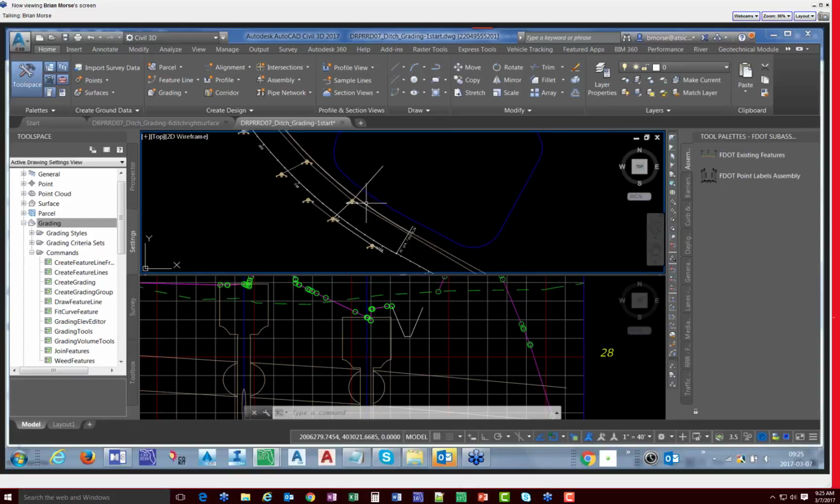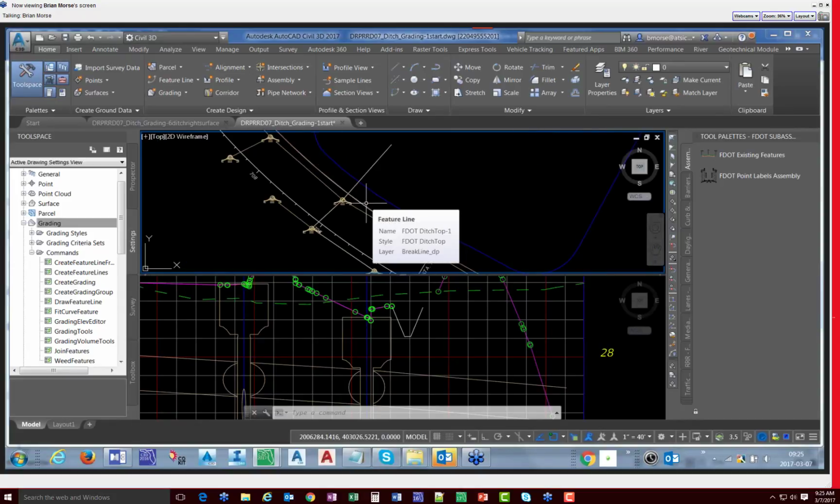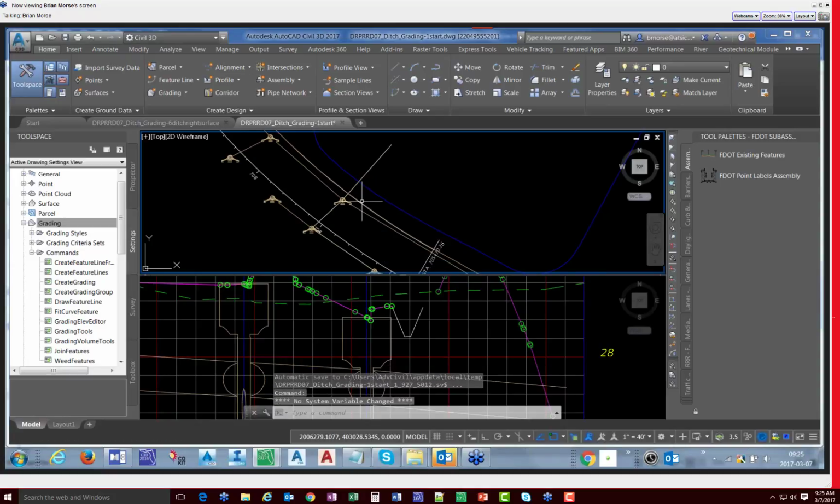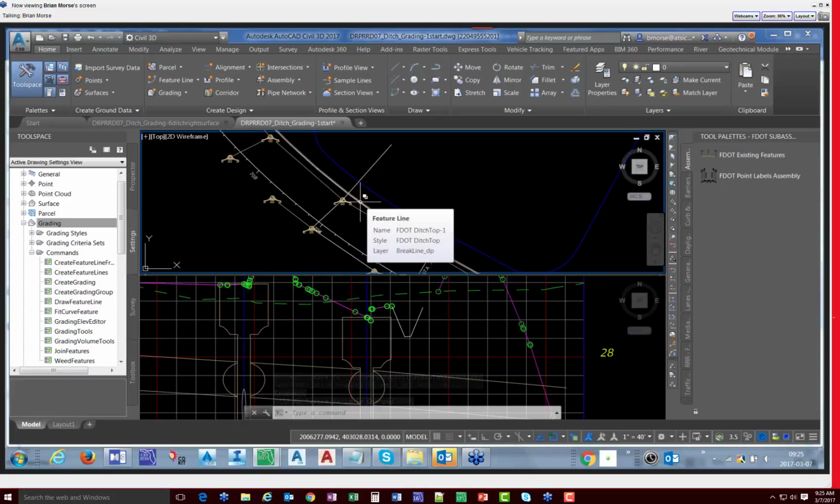So we're going to confirm this. If we go 49 feet plus, let's say we wanted to go 6 feet out, because that's going to be at a 4-to-1 slope, it'll be like 1.5 feet deep. So what's 49 plus 6? You got it, 55.